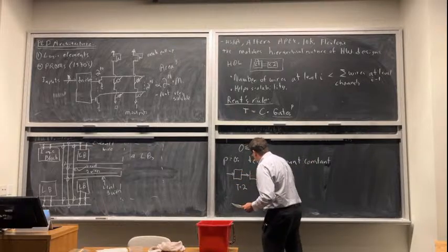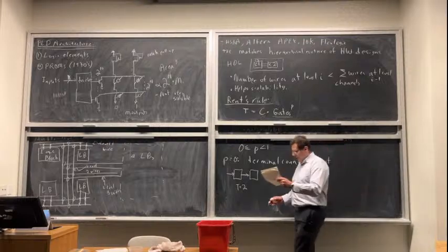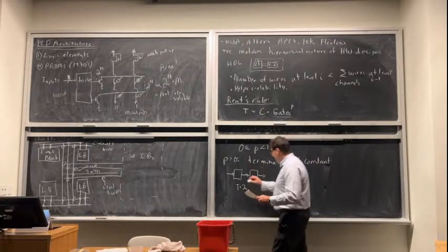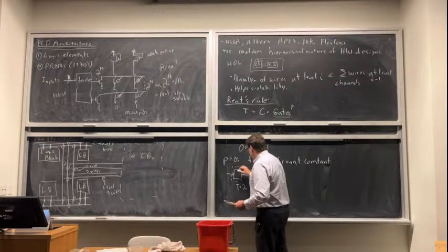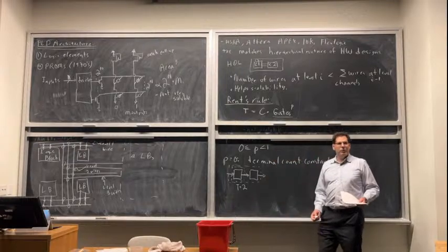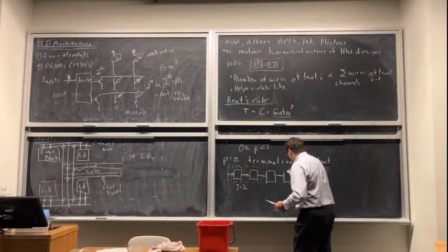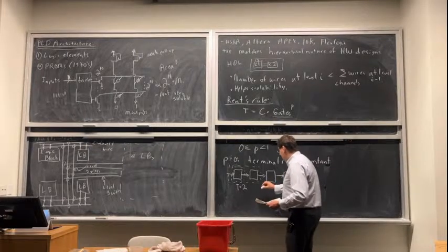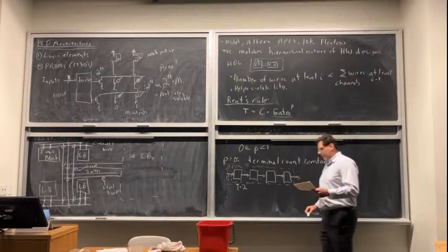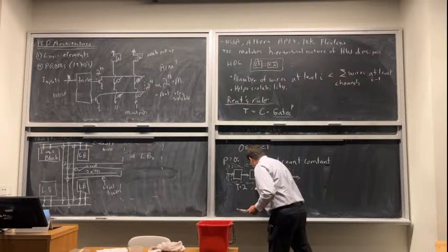If I have a long pipeline of signal processing operations to do, I find I can fit more of them on my chip. So I add one more block in the pipeline. Okay, so this was my first thing. Now I can fit more. This is the next level of hierarchy. Number of terminals is still 2, even though I have twice as much processing. And I can just keep doing this, right? So I add another level of hierarchy where I put 2 more blocks in. And if I draw a box around that, the number of terminals is still 2. Okay, so T equals 2, always.